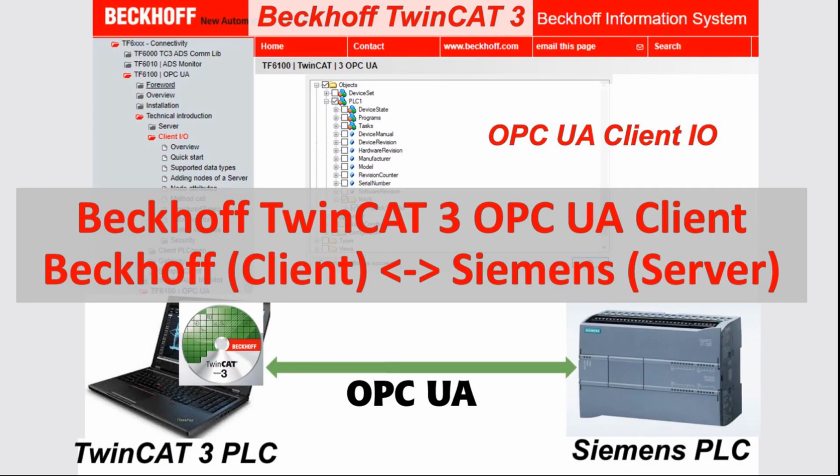Hello everyone, in this video I would like to show how we can implement the OPC UA Client function in a Beckhoff TwinCAT 3 system. In this test, I will use a Siemens S7-1200 PLC running as the OPC UA server, and I will use my laptop running as the TwinCAT 3 PLC and the OPC UA Client. So we can set up the communication between the Beckhoff and the Siemens, and communicate with each other via the OPC UA function. The Beckhoff side will run as the OPC UA Client, the master function.